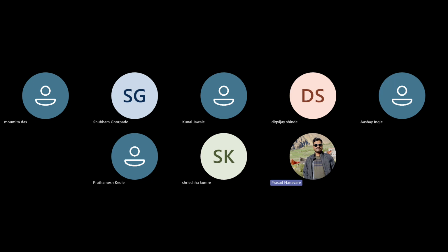Then we also saw how a task goes from running state to any other state, or from any other state to running state. A task can either be in running state or non-running state, and non-running is further divided into blocked, suspended, and what was the third one? Ready state, definitely. So, ready state is the mediator of all. A task has to be in ready state in order to run. These are a few things that you should remember.